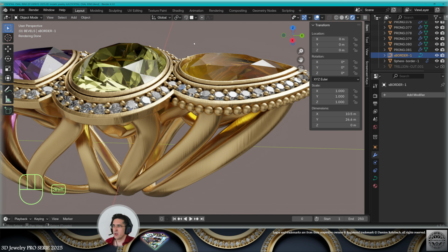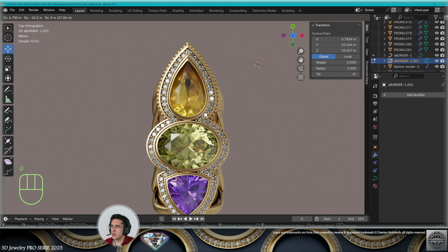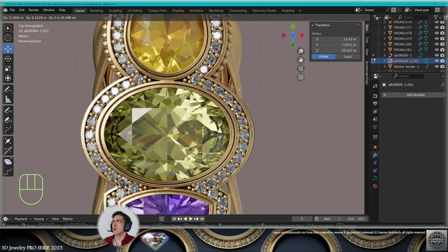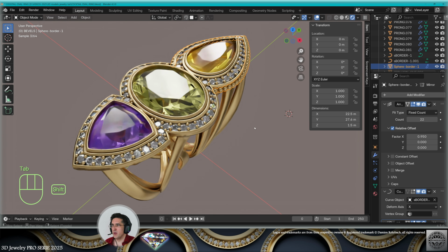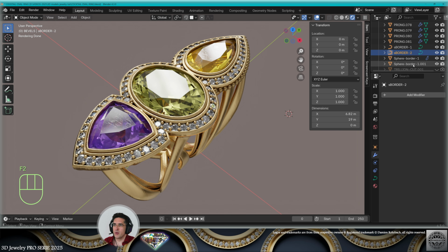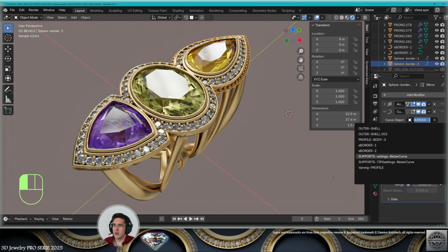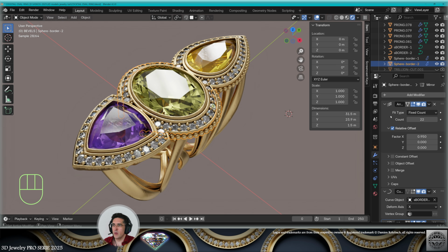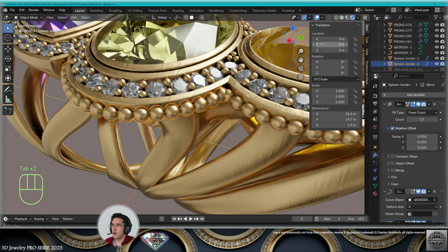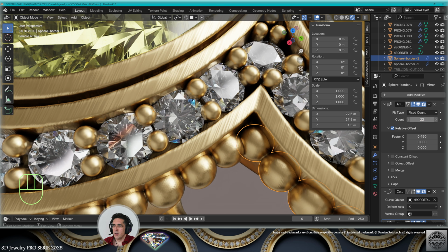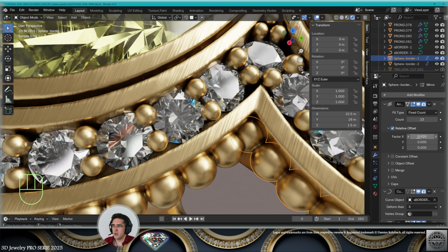So now let's copy the border and make the next border. Don't try to make them all at once. It's not necessary. You'll have more control on where the spheres start and end this way. So here, let's copy the spheres. Let's call that one border 2, spheres border 2, and the new border is border number 2. And so we can adapt the count. So you can move the sphere on the x-axis to make them start further away. Here I'm going to need one sphere more and less space between the spheres.